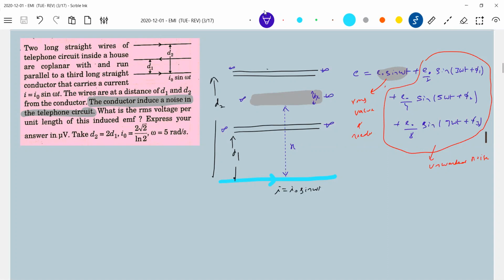Let's get into how to calculate the flux linking this. So d phi equals B into L into dx. Directly the B vector will be out of the plane here. So mu naught I, mu naught I L over 2 pi, dx by x. So this should be equal to the integral from d1 to d2.